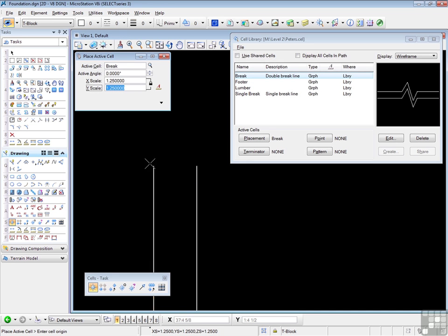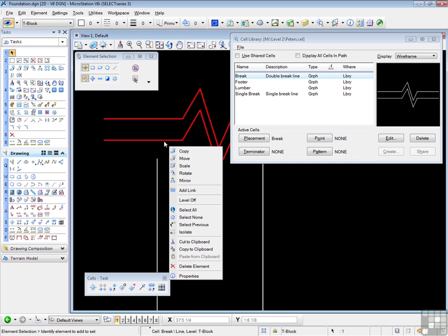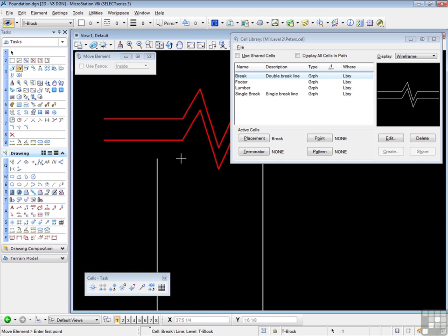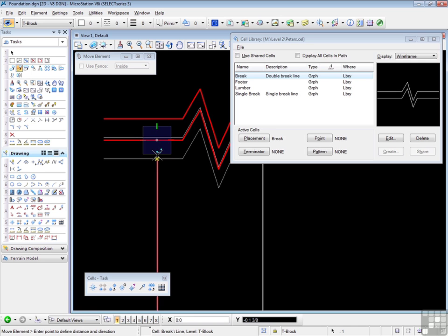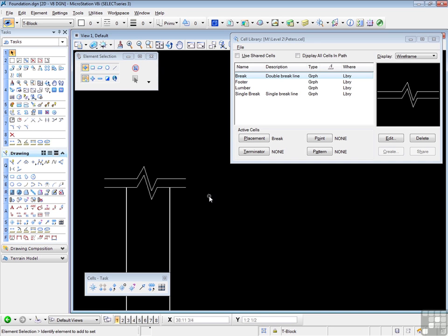That looks a little better. So I'm going to locate that roughly about there, proportionally. Then I'm going to move it. So we'll do a move. I'm using my multi-snap, so I will automatically pick nearest, and I can bring it down to snap to endpoint. Now that's nicely in place.